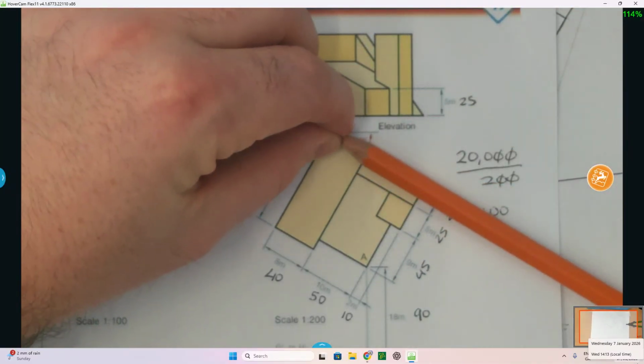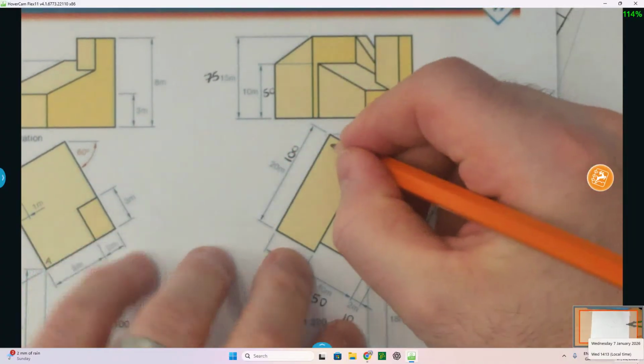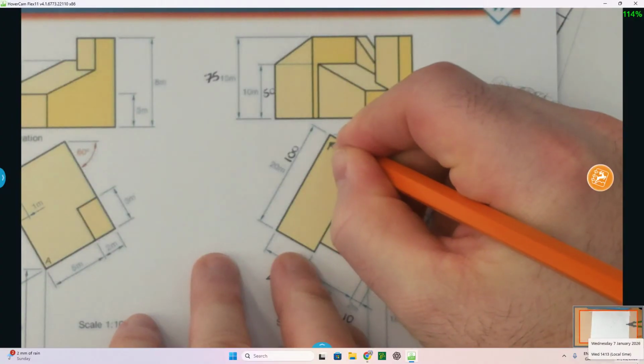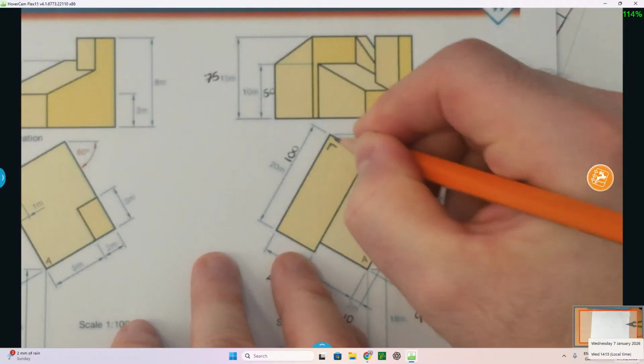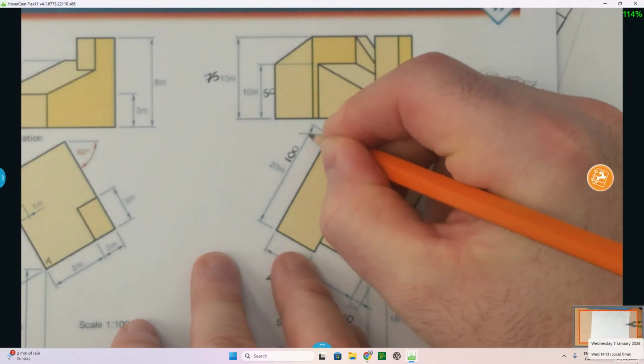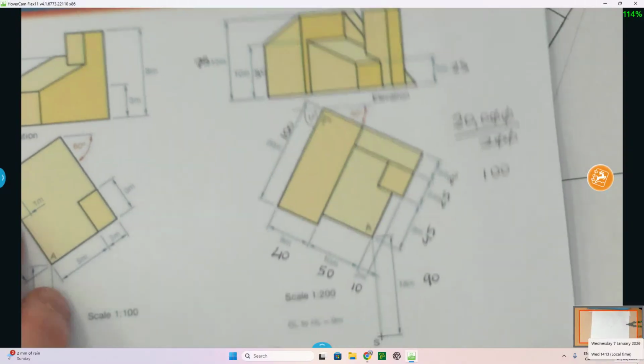I can see that the faces are going 30 degrees in this direction, and they're going to be going 60 down here. Why is it 60? Well, the reason it's 60 is because that angle is 90 degrees. It's a perpendicular angle. Therefore, 30 is here, with 90 in here, and if I continue the straight line out, the angle that would be left in here is 60. Okay? So that's the direction of my faces.